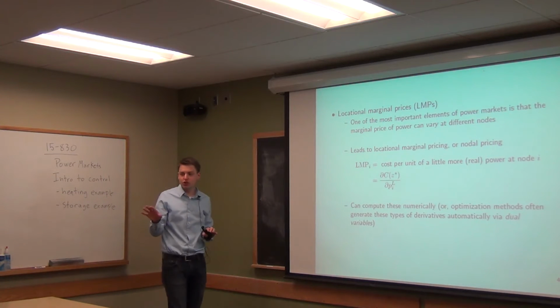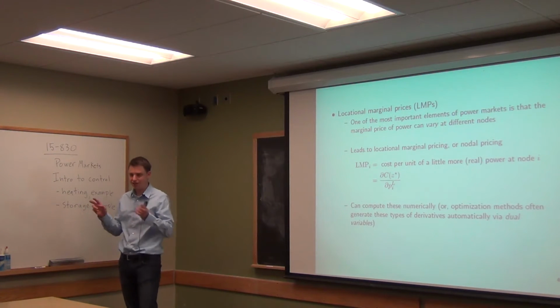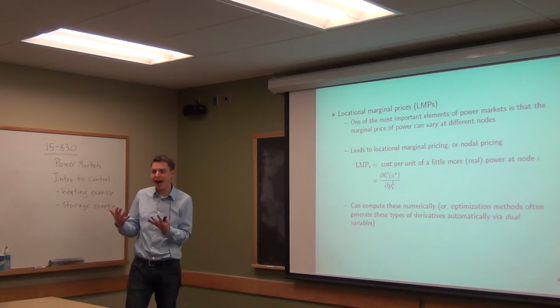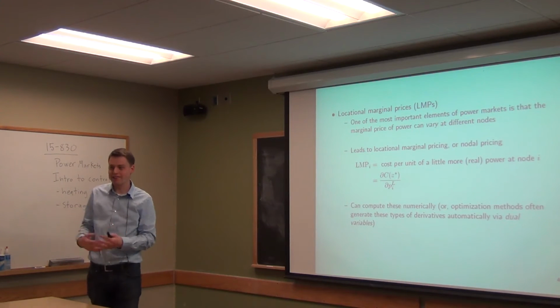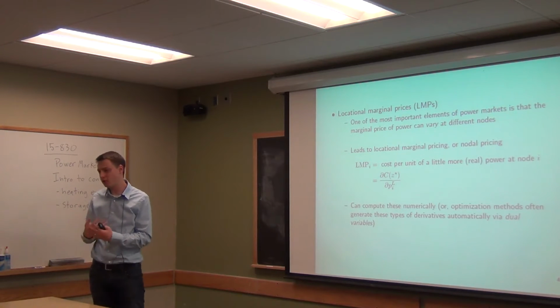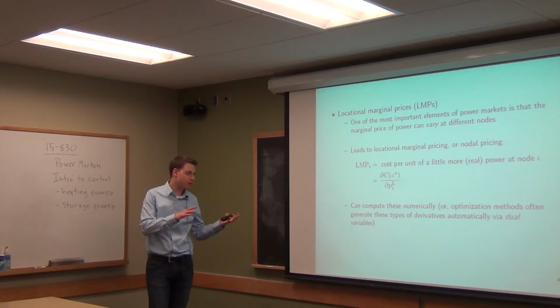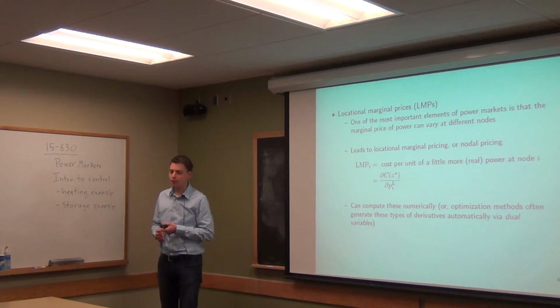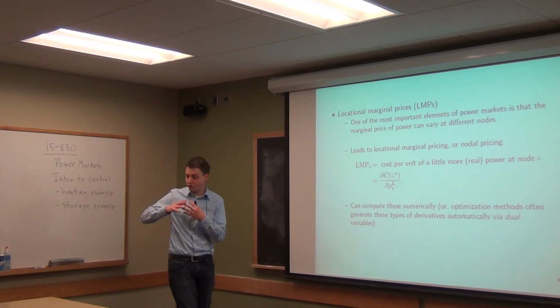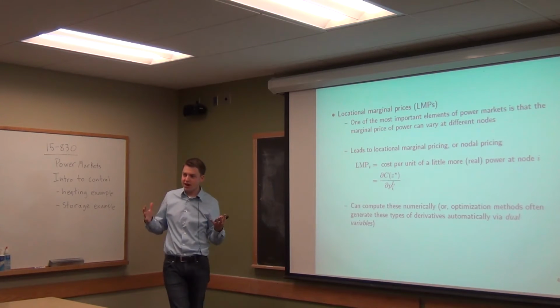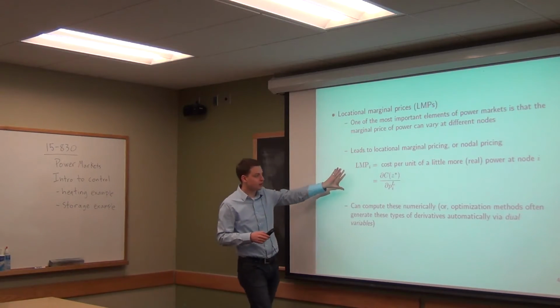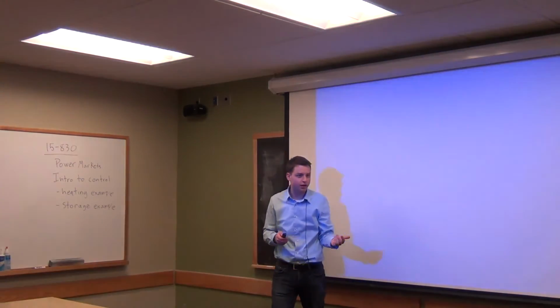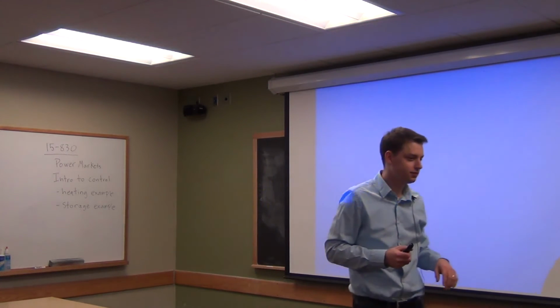What you do instead is use local generation, and generation is not quite the right word. Something like a capacitor, for example, could produce reactive power. You can do it with other things like voltage control and other mechanisms you can use to supply reactive power. But that has to be done locally. Because power markets are really about large-scale transmission and the cost for this, the LMPs are always done in terms of real power.